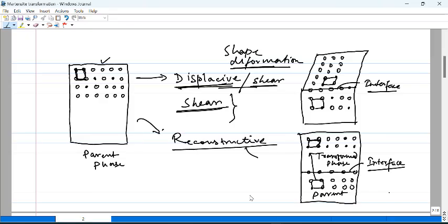Right. So we are back here, and now you can see that there is no force here. So you have to understand what is happening. See, if it is a mechanical deformation, the driving force is the mechanical force. If it is a plastic or elastic deformation, whatever it is. Okay, but here the driving force is the chemical energy, or the chemical free energy, or in other words, the Gibbs free energy.